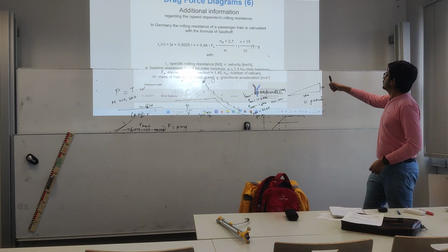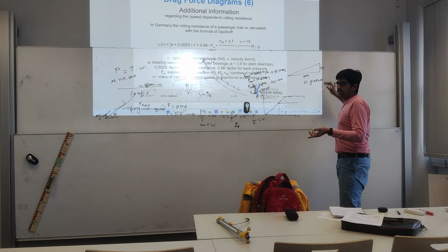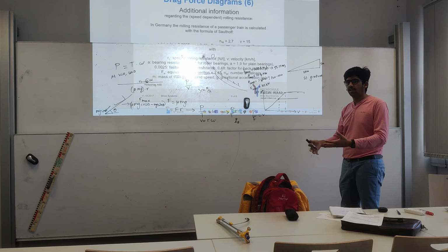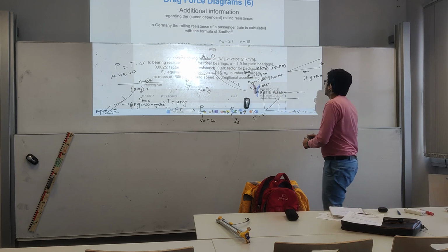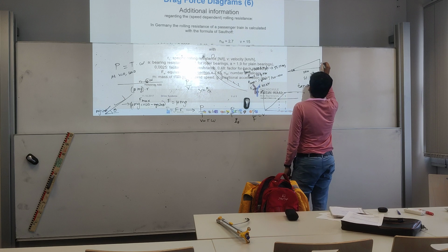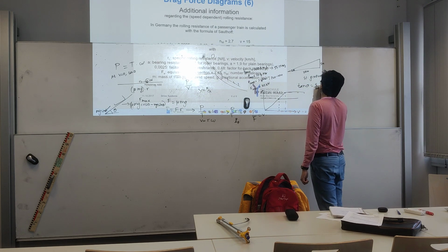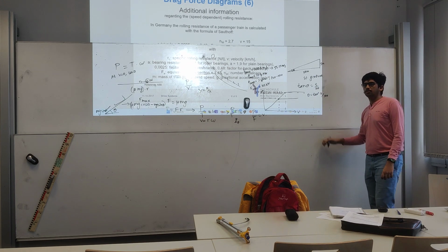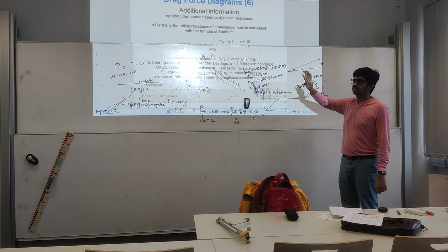So one important thing that you might need to know is how to convert this percentage gradient into an angle, because all our calculations are based on angles. Theta, tan theta is 5 by 100. Theta is tan inverse 5 by 100. Then you have the angle, then you can do whatever you need with sin theta, cos theta.